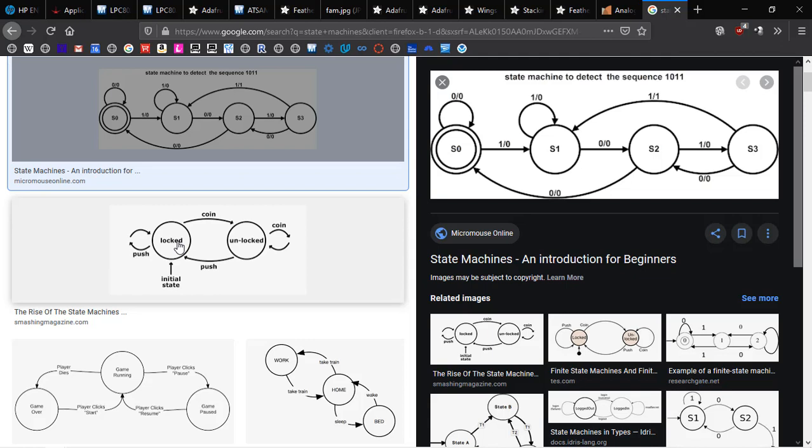You press the button again, and knowing that you were in the dim light state, it knows that you should go to the high light, the bright state. So even though it's the same input, you have to use the cross product, the combination of the current state of the system and whatever inputs are provided.